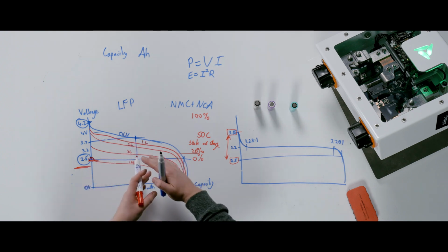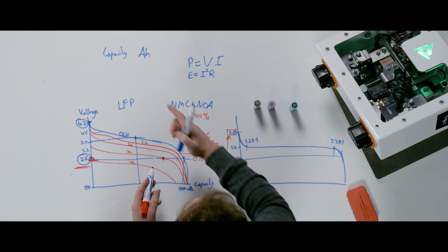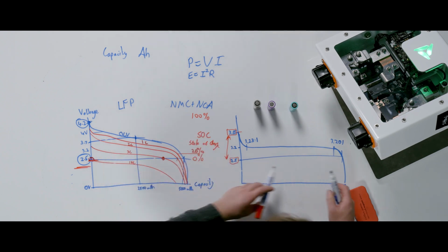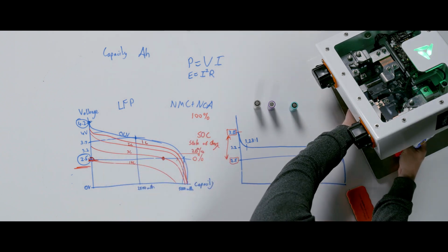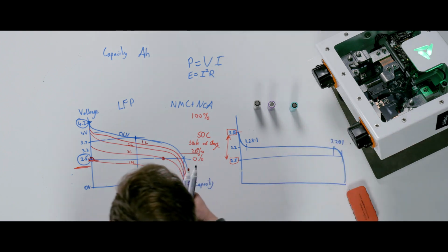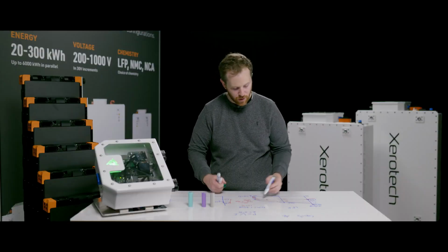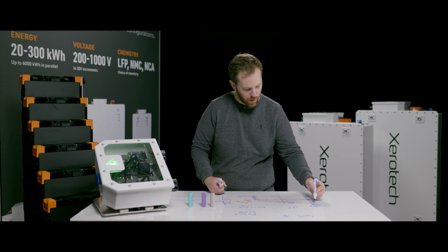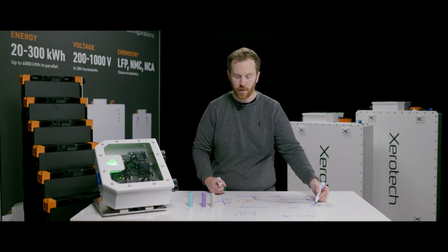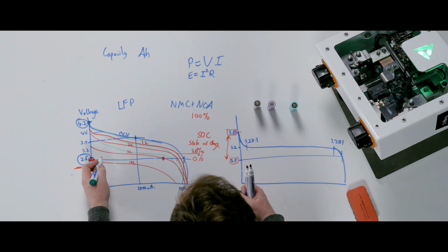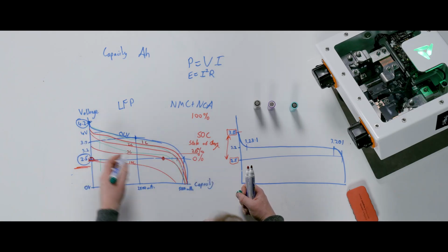And the exact same is true of charging, it's just reversed. So if you want to charge a battery, you actually get something called a voltage rise. So the terminal voltage will want to rise in that case. So you'd have a different curve going up the other way. So if a battery is nearly empty at 0% state of charge, you could charge at very high C rates because it's able to increase the voltage up high below this maximum voltage curve. So that means that when the battery is nearly full, up in this range here, you have to dial back